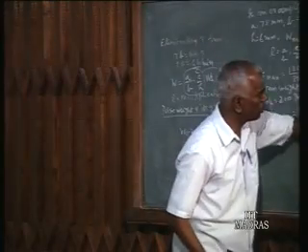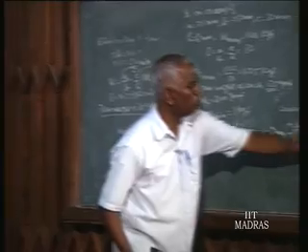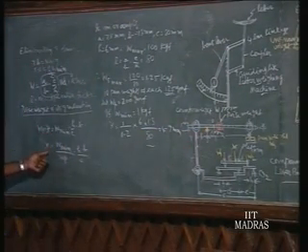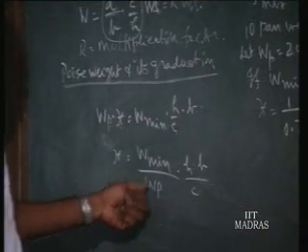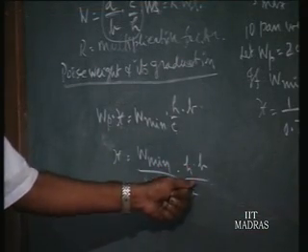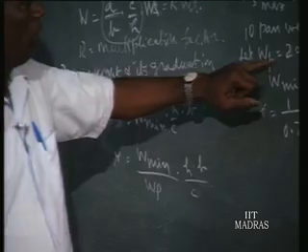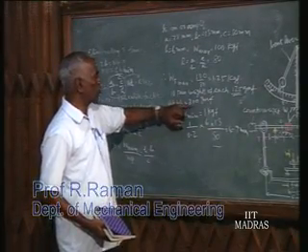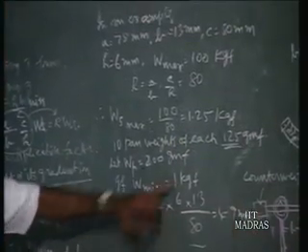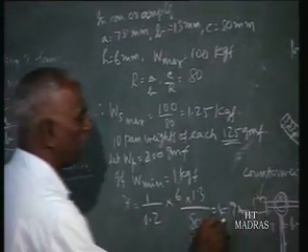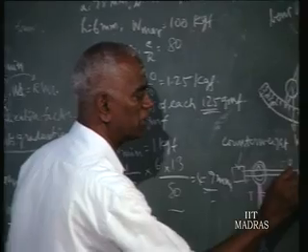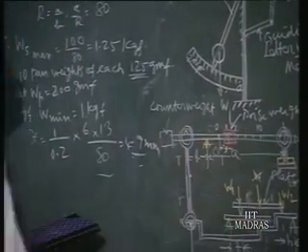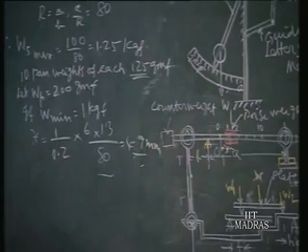Due to W minimum we have a moment here, and due to WP we have the moment WP into x. They are being compared, and we find x is given by W minimum H into B by C divided by WP. Now for this pan weight of 125 gram, we should have a little larger poise weight of 200 gram, and for this W minimum of 1 kilogram, x comes to about 4.9 millimeter. So every 4.9 millimeter distance we write 1, 2, 3 up to 10. So 10 kilogram means it will come here. That is how the poise weight and its graduations are finalized.